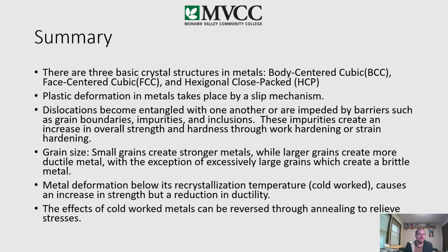All right. Last two here. Metal deformation below its recrystallization temperature is cold work. So this is where it creates strain hardening. It causes an increase in strength, but a reduction in ductility, like I mentioned. And the effects of cold worked metals can be reversed through annealing to relieve stresses. So that's a summary of really what I wanted you guys to get out of this chapter, the two-part